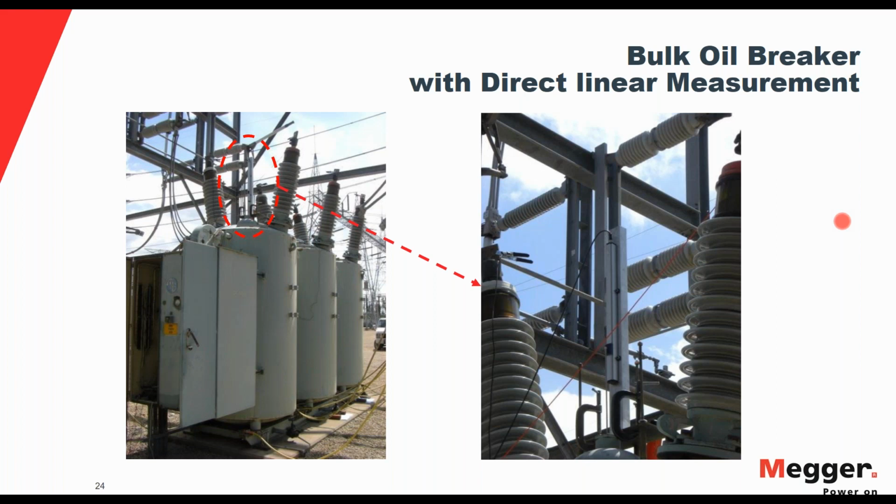Just open the mechanism and just operate the breaker. Just be careful with that. Apply common sense and see what parts you can connect to. Usually it's a handling arm or a gear that is rotating, moving an arm to connect or mount the transducer to.